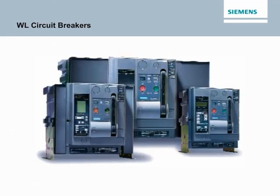Siemens WL family of circuit breakers has been designed to address the increasingly demanding requirements of today's power distribution system and incorporates the following characteristics: high reliability, compact size, ease of use, modularity of design, flexibility of system communications, safety-oriented features. The molded case circuit breakers discussed earlier conform to the UL 489 specifications.